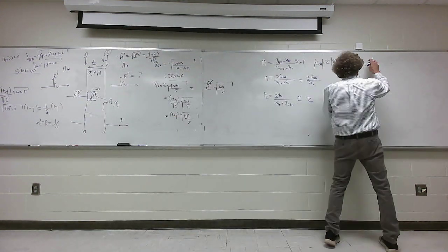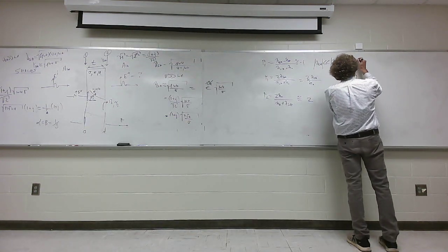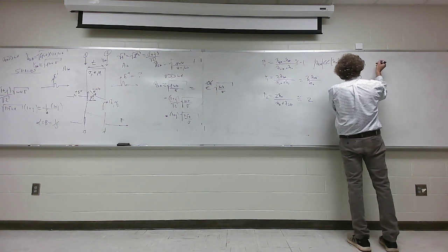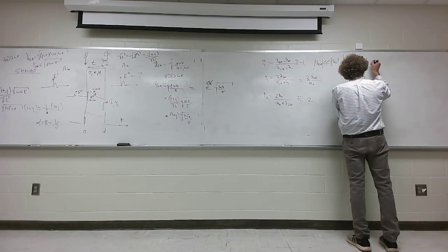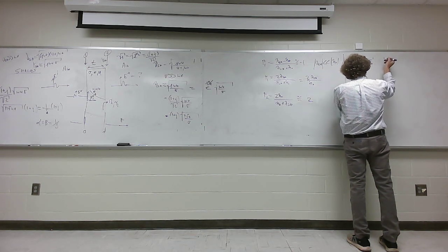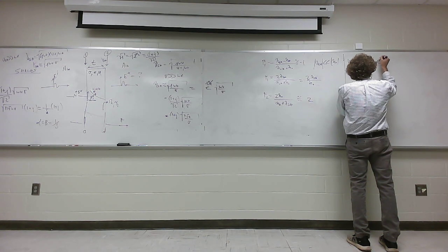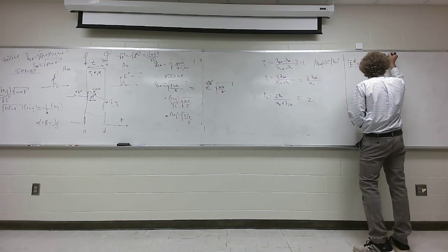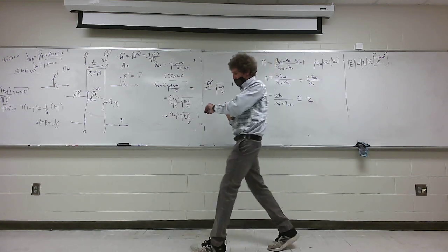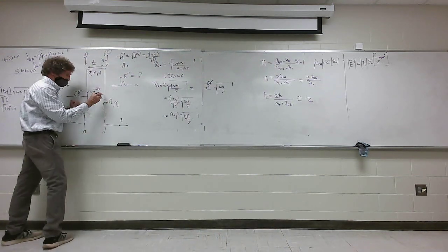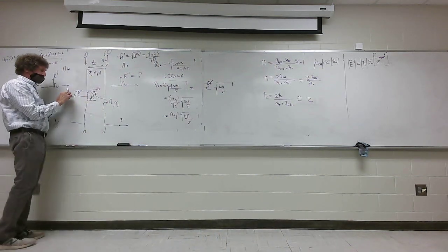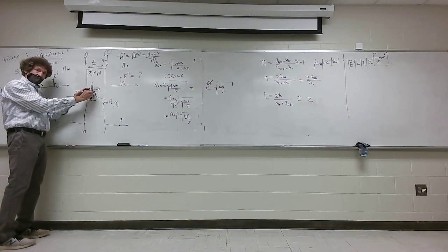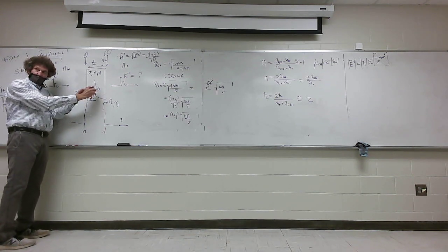So now that I have this, the magnitude, and here I'm going to do something. I'm going to put the magnitude of the transmitted field is equal to the magnitude of tau 1 times the incident field, and then it's going to be e to the minus alpha of the shield times the thickness of the shield. So now I'm right here, right? With me on that? Basically, I find out how much gets in, and then I let it exponentially decay as before, right?